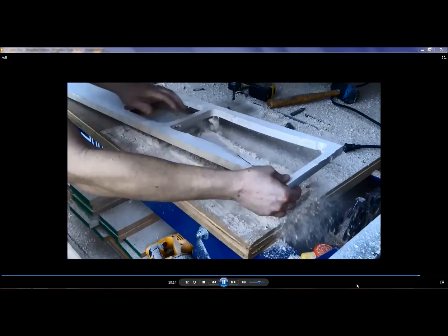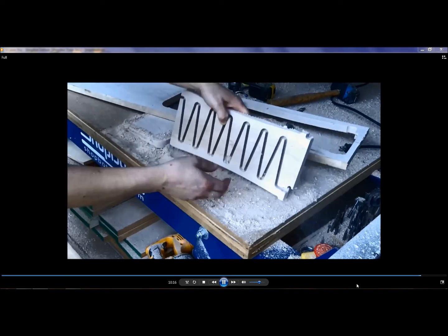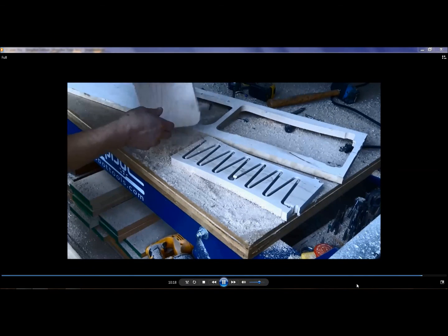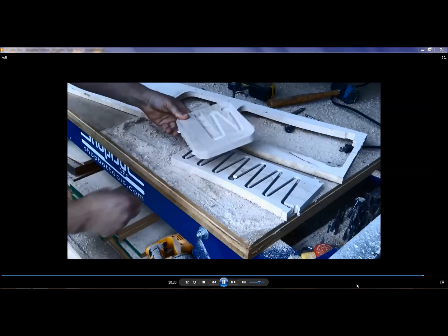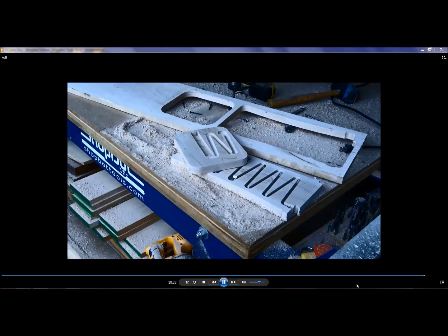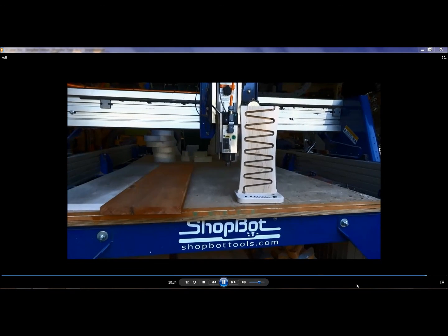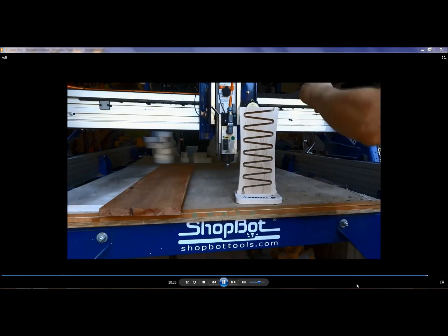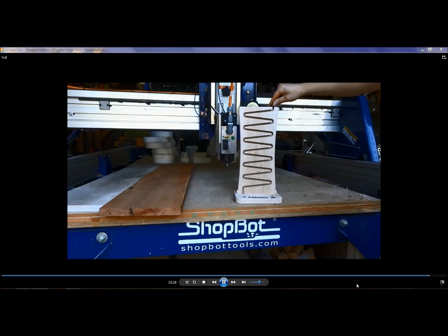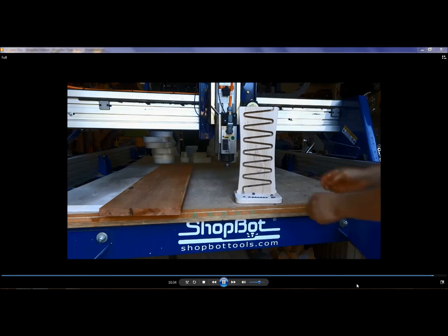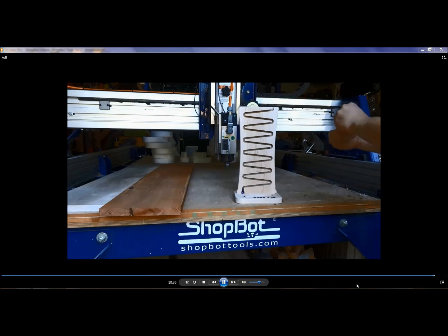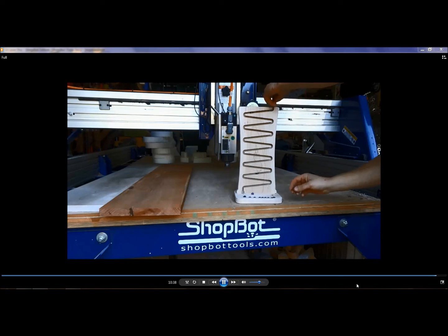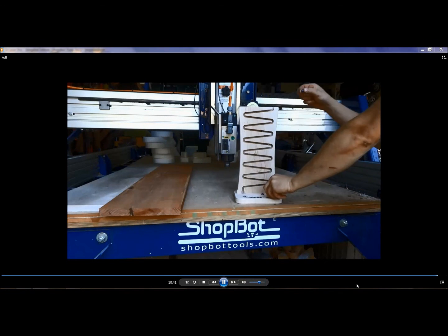So there's ramps, tabs, leads, and order of cut. These are some advanced options built into the profile toolpath that will help you come up with nicer features and cut a little faster and more efficiently. Here's the thing finished in the end. The marbles aren't coming out through the front because I had added the leads in. I've added the ramps to save on my bits.